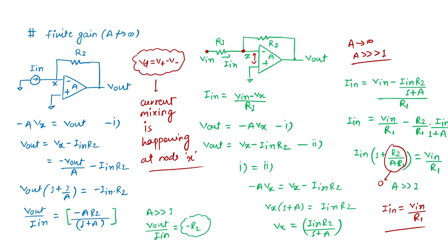So this is one topology of the feedback network that we will discuss in the feedback concepts. But right now I want to say that when input voltage comes as a part of the difference voltage, then what is the difference voltage actually? It is the difference of the inverting and non-inverting terminals of this amplifier.